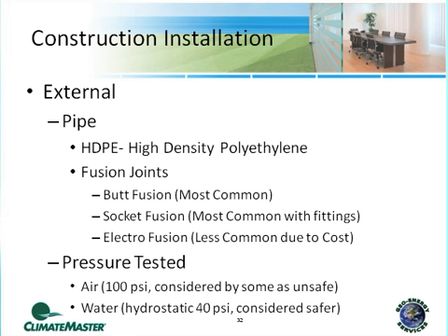Once that's done, you can carry that information forward, and we've got the information we need to carry forward to the Borefield design. Now, as far as installation information, what you should be aware of externally: all that high-density polyethylene pipe is heat fused in the ground. There are no joints out there that are soldered or welded together or have pipe threads on them.